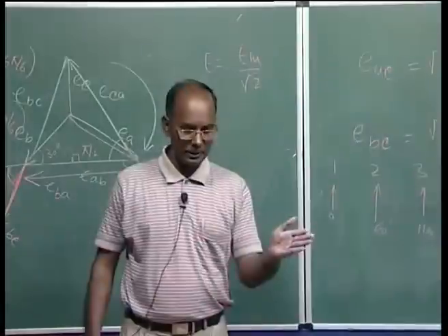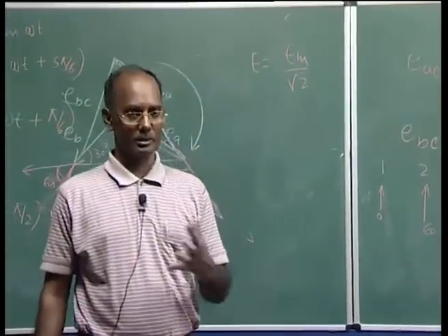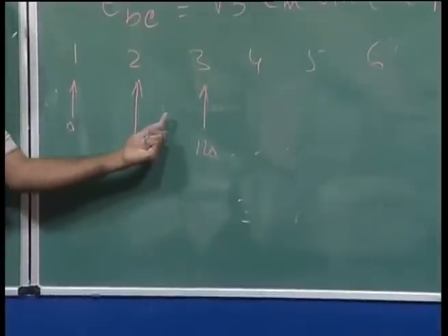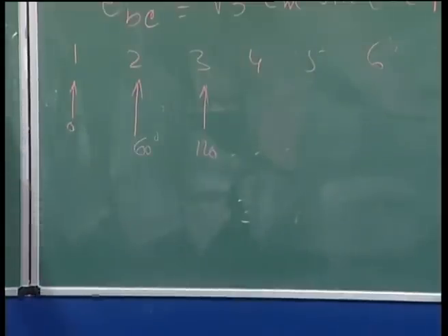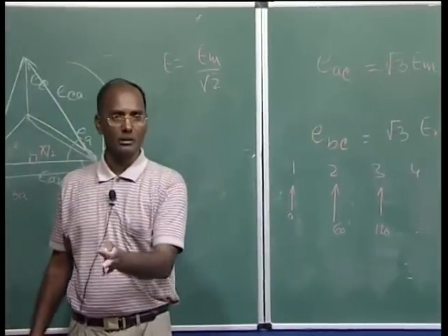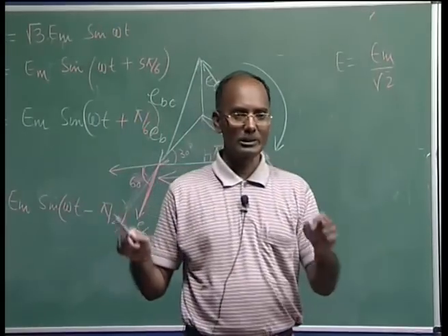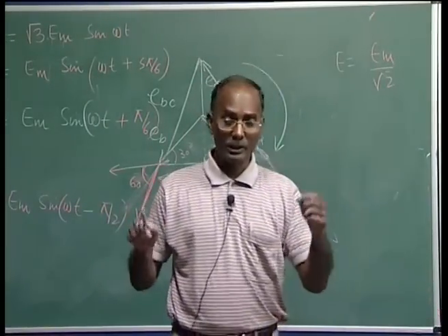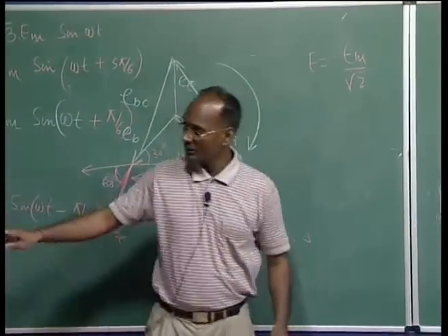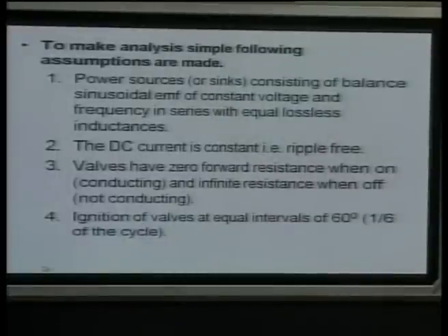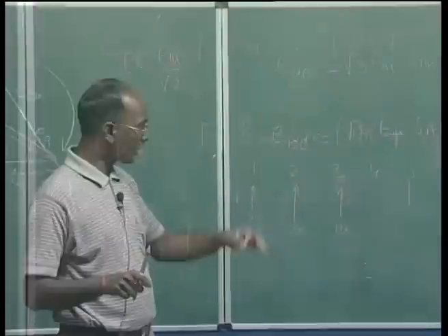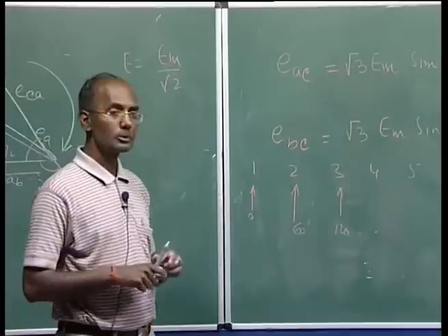Here we are assuming the symmetrical conduction pattern that is appearing across the converter circuit. It is possible you can delay; here it is 0, you can give this valve a pulse after maybe 60 degree. But we do not want that, because if you are delaying, it will conduct if the commutation voltage across it is positive, even though you give the pulse after certain degree, but your output pattern will not be symmetrical and it will give a lot of harmonics to your system. Current will be something different, so we never want it. We always operate in a very systematic manner. So, this assumption shows that we are giving the valve pulses to the consecutive valves after every 60 degree, so that we can have perfect ripples in the DC output and also our conduction pattern should be symmetrical.